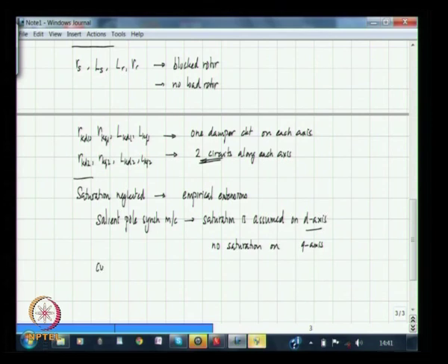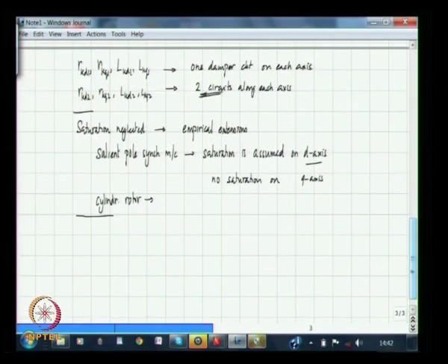But on the other hand, if you have a cylindrical rotor machine, then you can have saturation on both the d and q axis, and therefore one has to devise ways of accounting for the extra excitation that is necessary to produce the flux, and that can be done in various ways, as one can see in the literature. These machine models that we have derived are useful again in various domains. Some of them we have seen: control systems. Synchronous machine models are very useful in large system studies, stability studies, and so on.